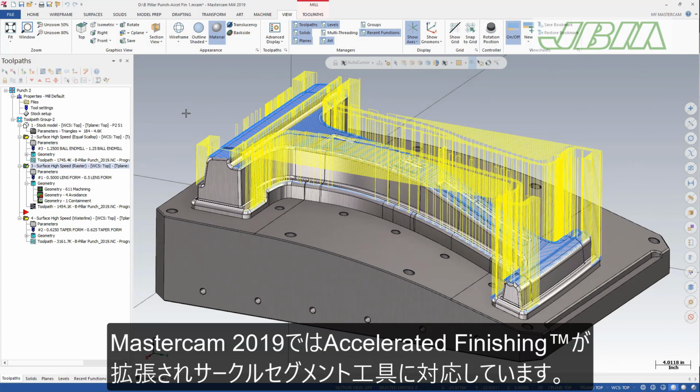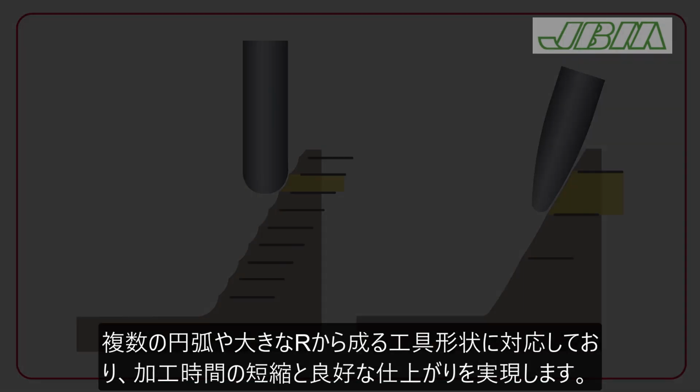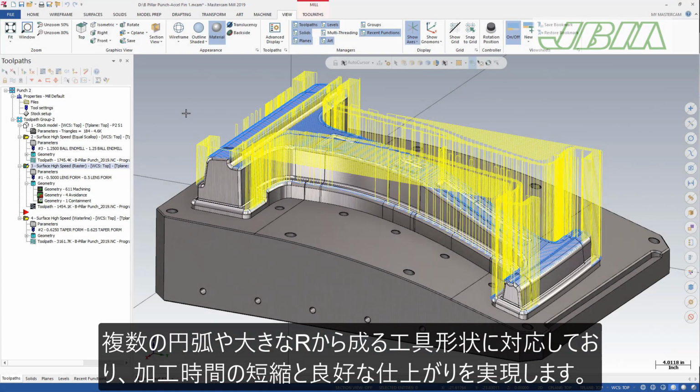In Mastercam 2019, Accelerated Finishing has been extended to support new circle segment tool geometries. In addition to barrel form tools, Mastercam now supports lens form and taper form tools. Circle segment tool profiles include multiple radius segments as well as large radius segments on cutting edges, which can deliver faster results with a better finish.